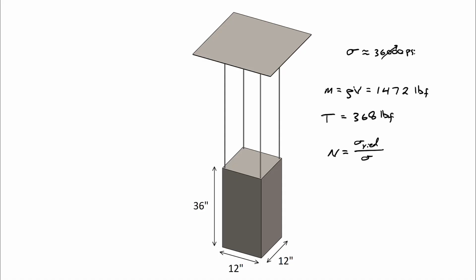Okay, let's change it just for the simplicity of the calculation. Let's change it to 30,000 psi or 30 ksi. Sure, we can absolutely do that. So if we set the yield strength to 30,000 psi or 30 ksi, it just makes the math a little simpler. With that in mind, we'll design the rod so that when it's carrying the load, that includes our factor of safety, the stress in the rod doesn't exceed that 30 ksi. So let's go ahead and do the final calculation and figure out what diameter we need.